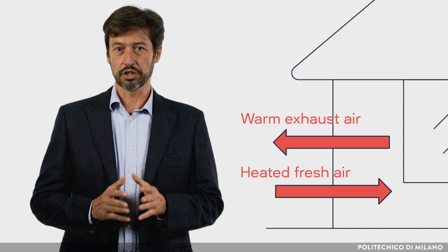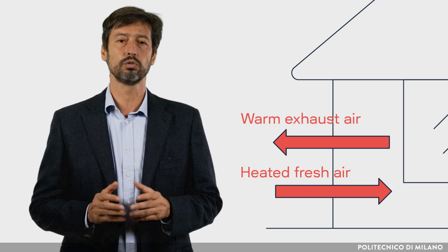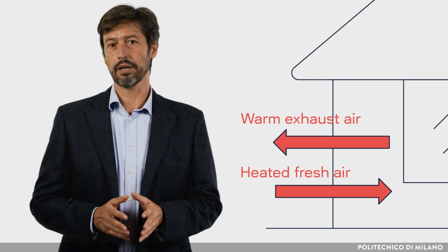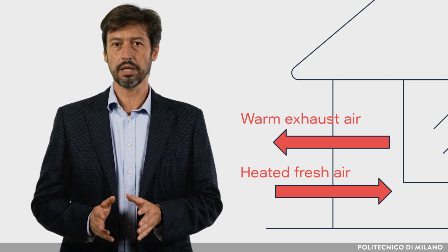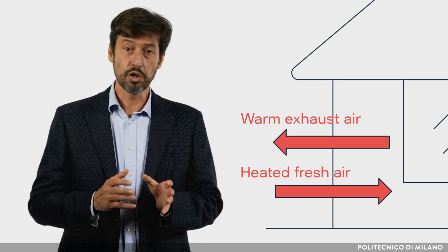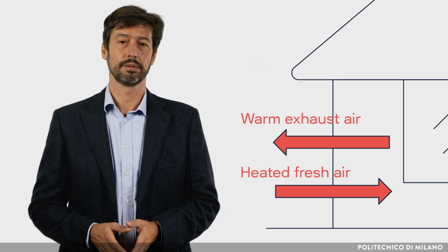Exhaust air, while generally polluted, already has the temperature and the humidity of the controlled space. On the other hand, fresh air has the condition of the outside environment and needs to be heated, cooled, and humidified or dehumidified before being supplied.